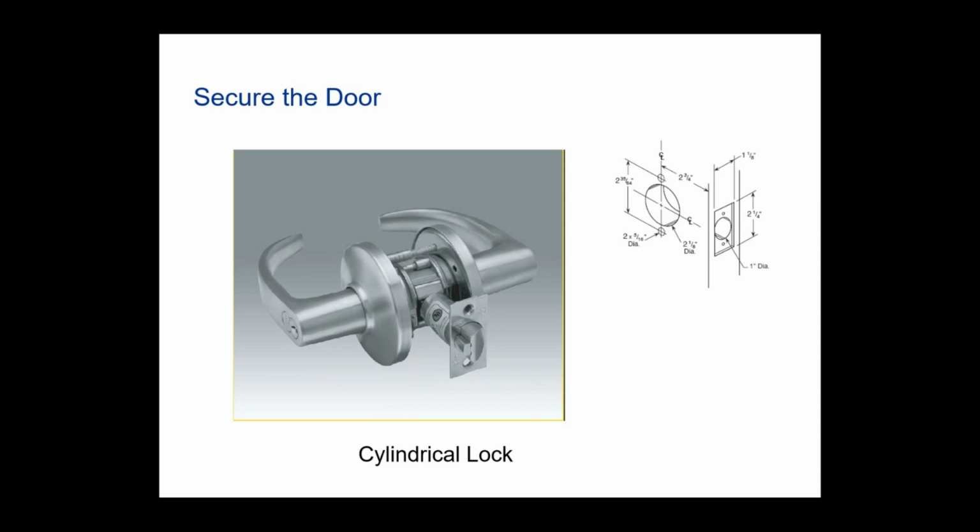The latches can come in various depths. The most common in our industry is 2 3/4 of an inch, but in residential or in light use commercial, you'll see 2 3/8 of an inch back set. And also you might see in special applications where you have maybe a very heavy duty sound door.